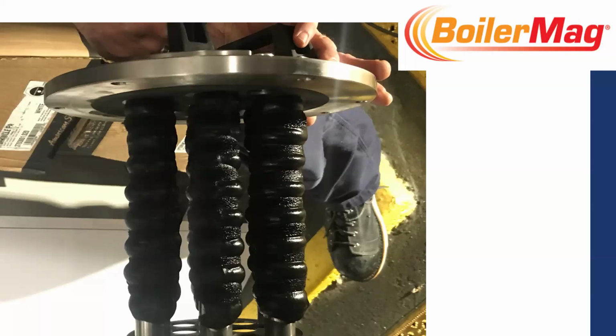Years ago, we probably didn't do it because we weren't putting magnets in the system. We were doing this different technology. As this technology is being accepted and embraced, we just want to make that last step to protect. So these boiler mags or these different magnetic filters are like the sacrificial lamb. They're intentionally there to grab all that iron oxide so it doesn't show up on the heat exchangers of the boilers or in the volute of the circulators.